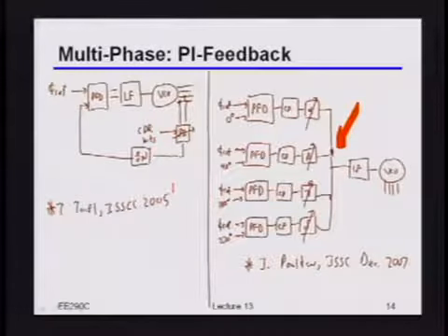Maybe this doesn't matter, but any mismatch on the paths on the feedback, or at least for the dividers, I guess the adaptation, the CDR adaptation, takes care of it? Well, no. If there really was mismatch on the feedback paths, that's going to translate into errors on the step sizes of your phase interpolation codes. If the errors on the feedback path are sufficiently small, meaning your worst case steps are still within the range you want, then it's basically fine. I wouldn't necessarily say it's more tolerant, because those errors would have caused the same effect even in these other kinds of architectures.